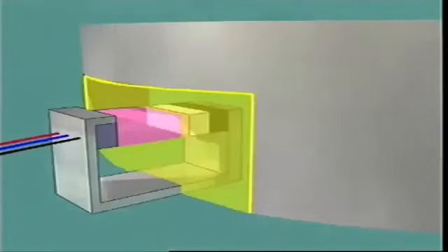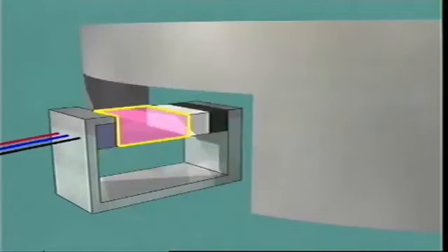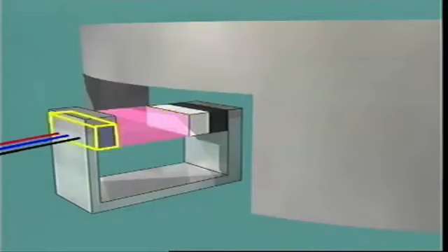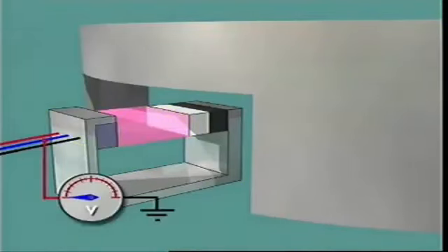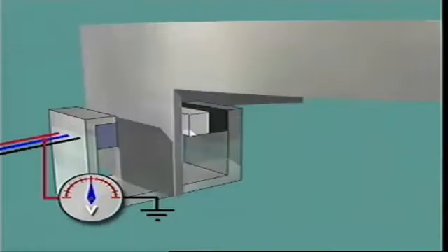When a window is aligned with the assembly, the magnetic field is at its strongest, and its lines of magnetic force permeate the Hall generator and its integrated circuit. This allows the generator to switch to ground the low current signal voltage applied to it. When the interrupter ring rotates so that the blade aligns with the assembly, the magnetic field is shielded from the generator and the signal voltage is not switched to ground.